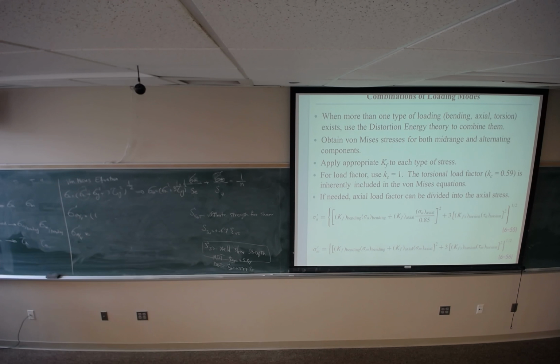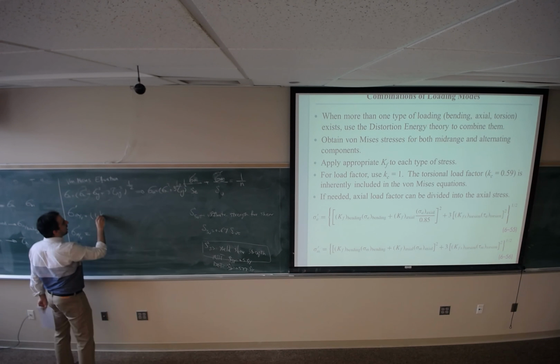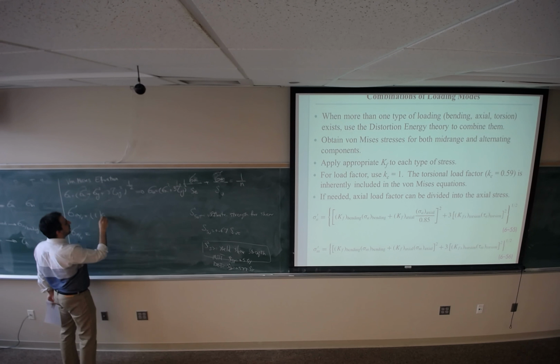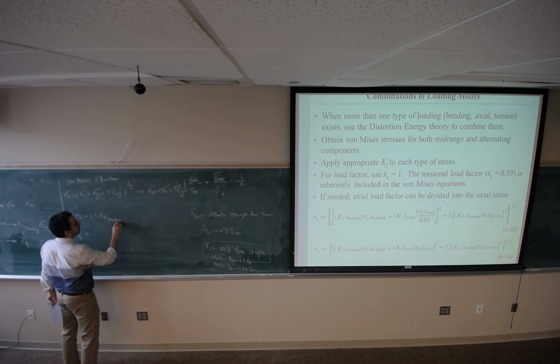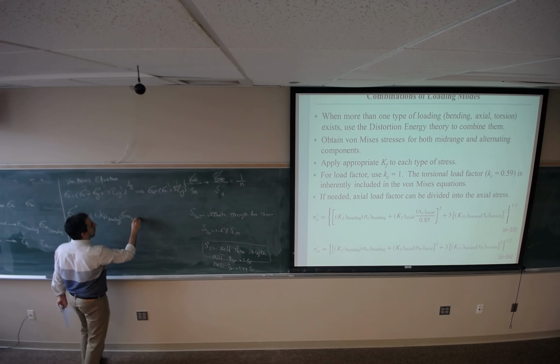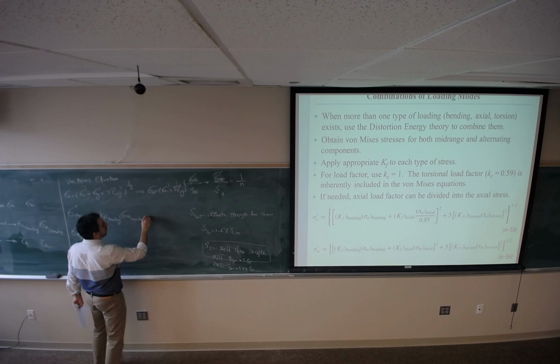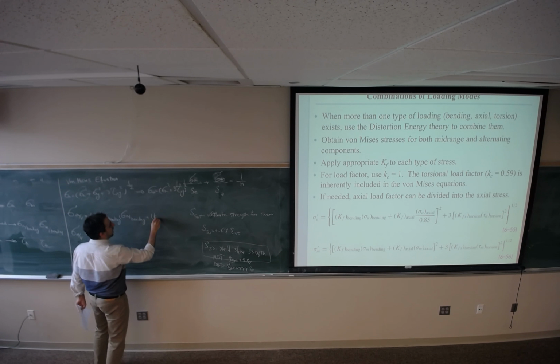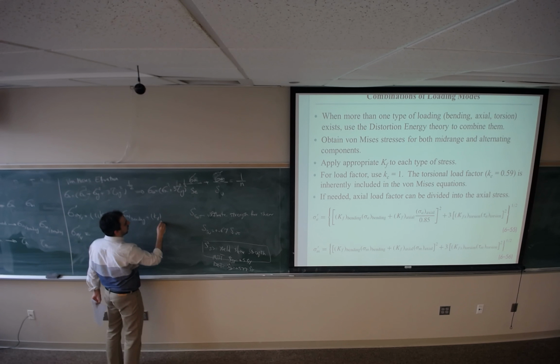So Kf for bending multiplied by sigma A for bending plus Kf for axial multiplied by sigma A for axial divided by 0.85.